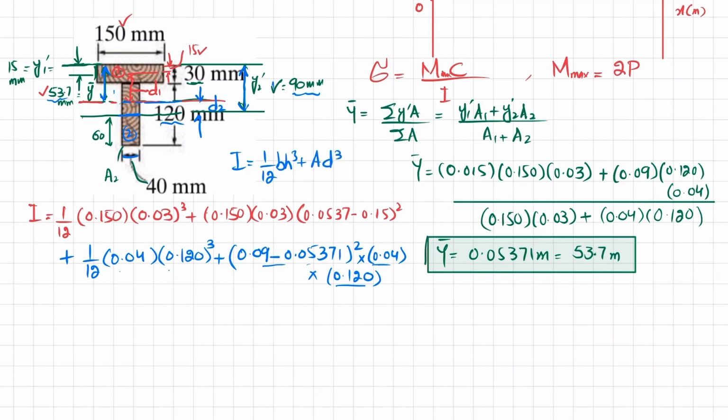when the centroidal axis does not pass through the centroid of the object, D square. So when you calculate it, you will get the moment of inertia comes out to be 19.162 into 10 raised to the power minus 6 meter power 4. So this is your I.